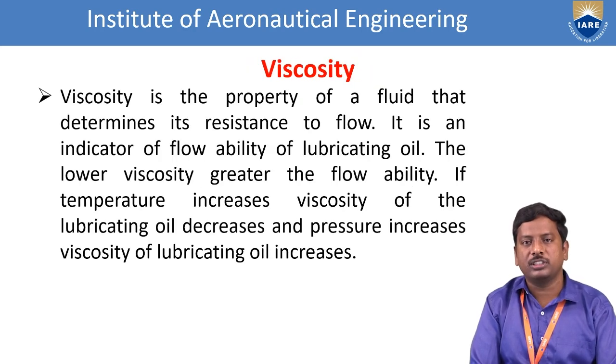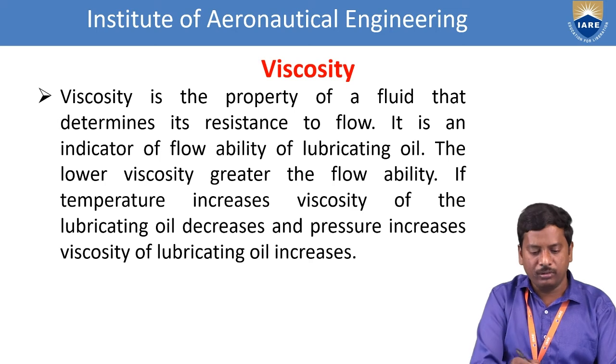Now, after that, we see the viscosity of the lubricants. This is one of the important properties. Viscosity is nothing but the dragging force between the two layers. That means viscosity is the property of a fluid that determines the resistance to flow, and it is an indicator of the flow ability of lubricating oil. The lower the viscosity, the greater the flow ability.